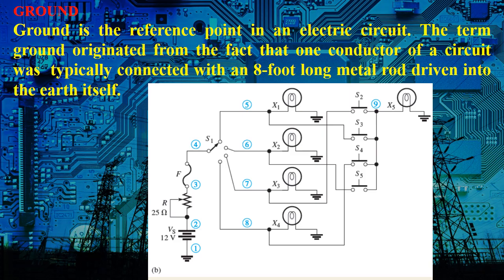So in the case of a fault, the current quickly goes to the ground conductor and to the earth for safety reasons. You see that grounding symbol there. That means the circuit is grounded. You can ground the source, the voltage source. You can also ground the load side of the circuit.